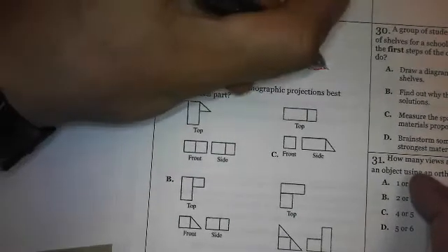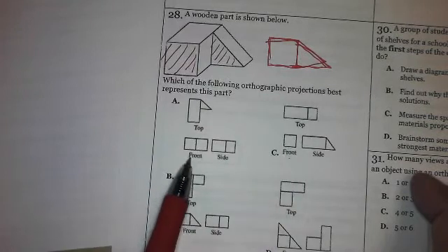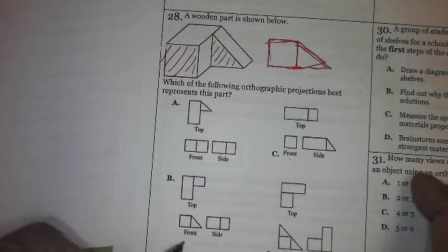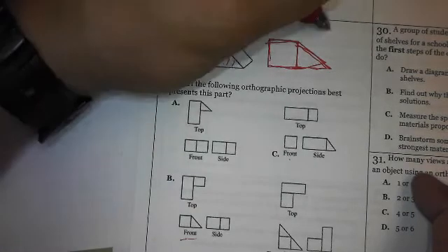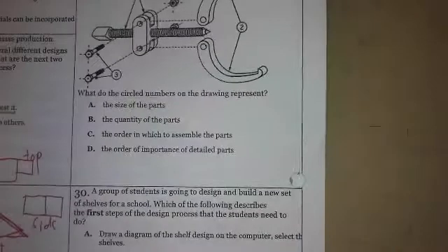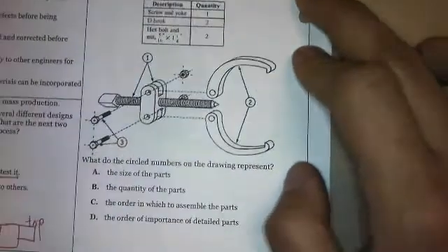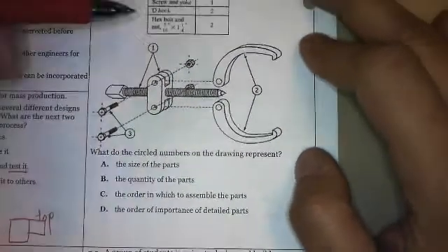Okay, which of the following orthographic drawings, orthographic projections, best represents this pair? So here, if we just look at the front, this is going to be the front. That's one way I look at it. It's a bad drawing here, but let's go with it. Which one looks like the front? Okay, let's do some more investigation. The side would have this and this, so the side should be that, and then another little triangle like that. And then the top would be this and that together. So the top would look like something like that. Yep, B. So this is front, side, top. Front, side, top.